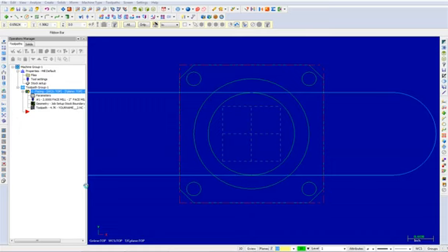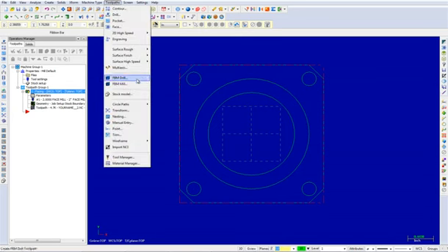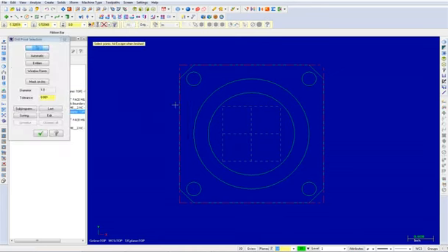To remove the toolpath display from your screen, press Alt-T. Select Toolpaths, Circle Paths, Circ Mill. From the drill point selection, click on Entities. Now choose the 1.5 inch diameter circle as shown. Once the entity has been selected, choose the OK button to exit the drill point selection dialog box.